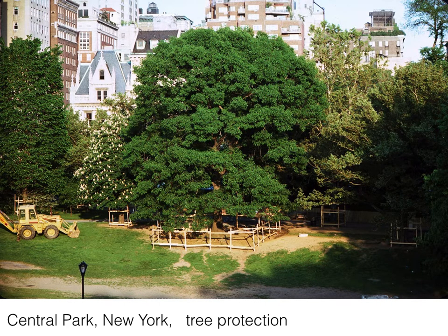You'll see the fencing around that tree trunk. That's the tree protection, so that even while they're working on the site, they don't want anyone driving heavy equipment across those roots. If you compact the soil on roots with bulldozers and such, that itself will probably kill the tree. It'll take longer to do, but it will eventually happen.